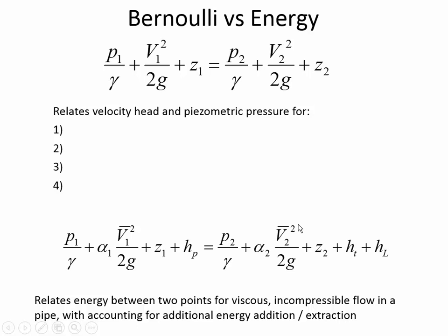Now, first of all, the pressure head term is the same. Do you remember what was one of our good problem-solving tools when we were applying the Bernoulli equation? What would we try to do when we're picking where is 1 and where is 2? Like, what would make the most sense when we're applying Bernoulli's equation? What would we sometimes do in picking 1 and 2? Exactly right. So we'd want as many of these terms to be 0 as possible because we don't want to have an unspecified equation where there's too many unknowns.